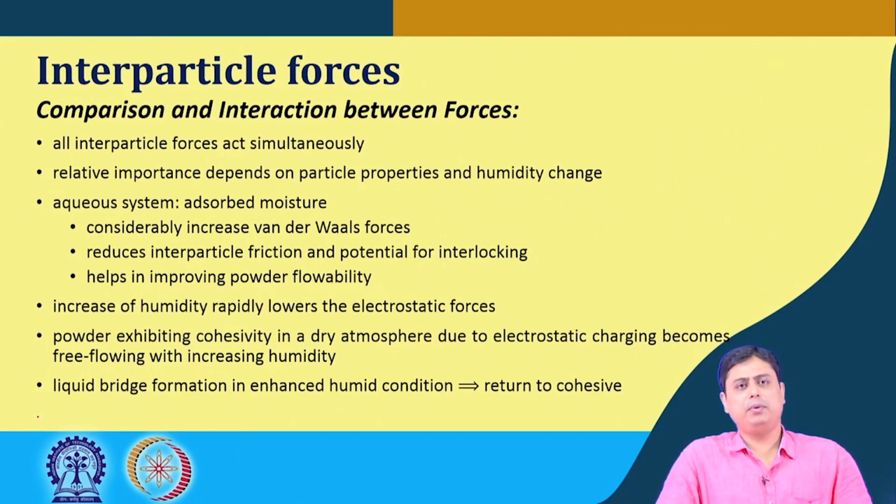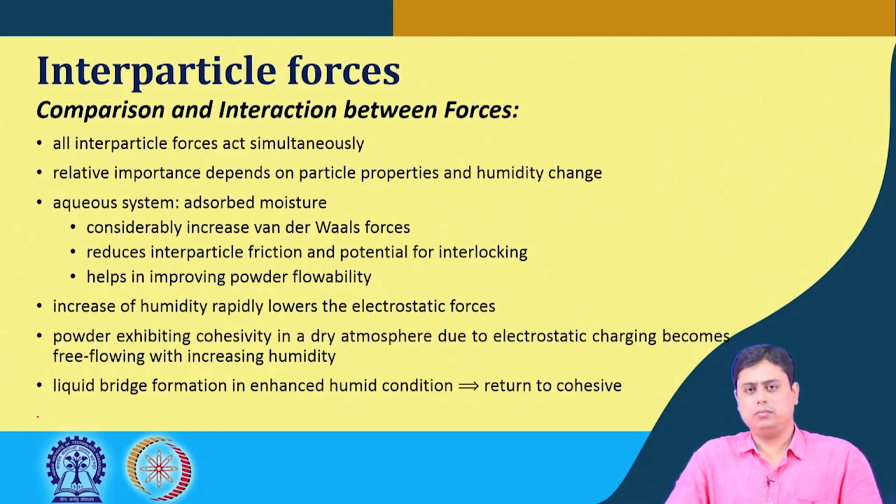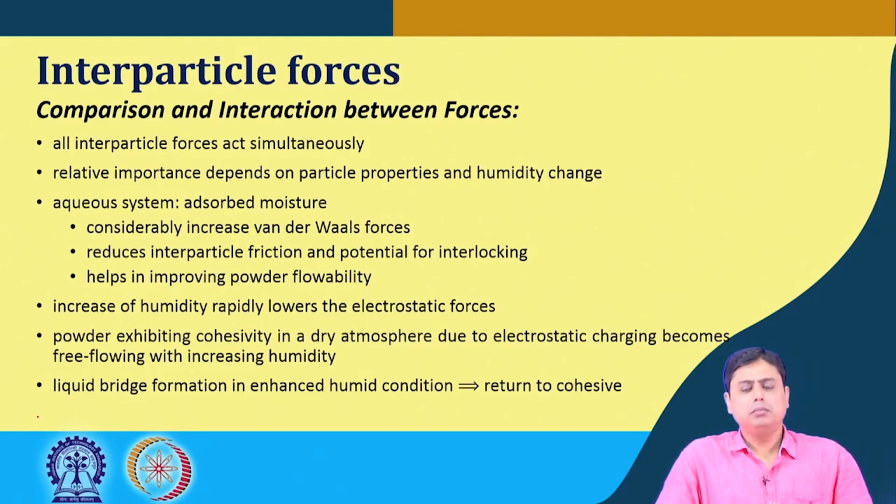But it can help in improved powder flowability, because these fine particles, or we can say powders, due to their cohesive nature or adhesive nature, sometimes it is difficult to flow, but the presence of humidity can improve its flowability. But studies have also shown that if we increase the humidity to a greater extent, then the powders can return to the cohesive kind of state.